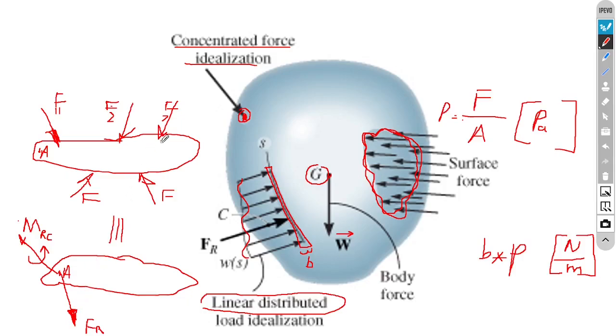In all the cases, whatever the statement of the requirement is, the things to do are the same. Find the resultant of the given forces, of course, vectorially adding up. If the forces are coplanar, while using scalar expressions, we can find the x component of the resultant and the y component of the resultant, and then using the Pythagorean theorem, find the magnitude of the resultant.